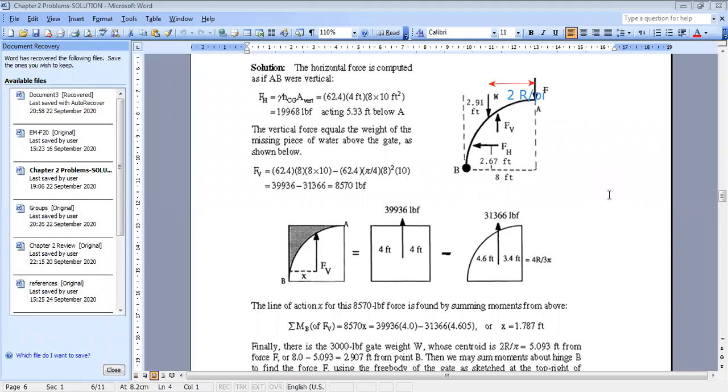The final step is we want to ensure equilibrium. To ensure equilibrium, the sum of moments about point B should be 0. Why did we select point B? Because the hinge will represent two reactions, By and Bx. In 2D equilibrium, you can solve for 3 unknowns, if you remember from statics. You can find Bx, By, and your force F. Here, because we are not interested...